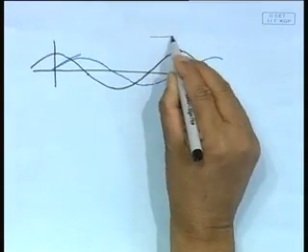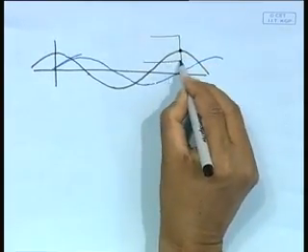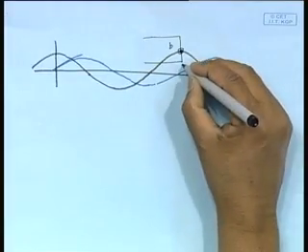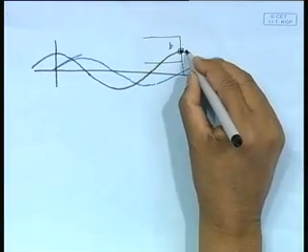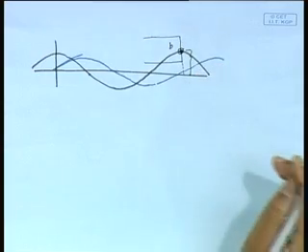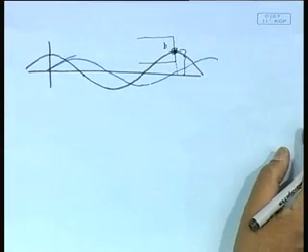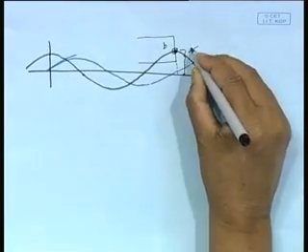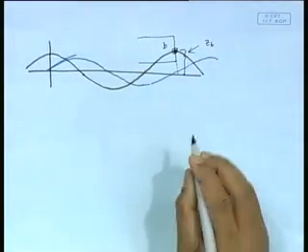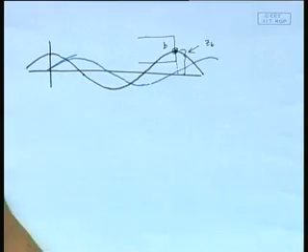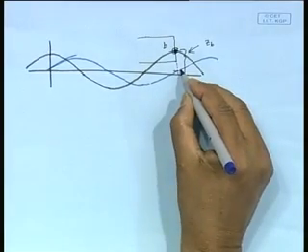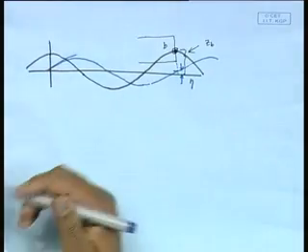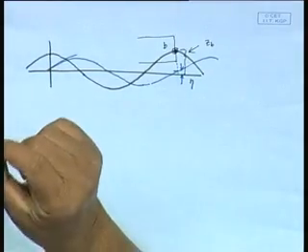So supposing I take a point here on the bow, say point B. At this point, this height is my vertical displacement of point B, so let me call it Z at point B, whereas this blue line is eta at that location, that is the incident wave height.